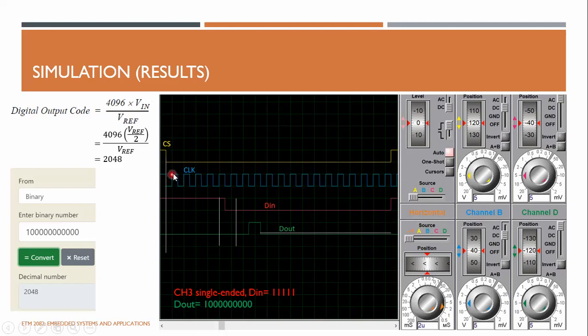Using delays and the right frequency, you can set the other clock pin low and high likewise. During this period, the DIN could be set to high or low depending upon the input channel and whether it is differential or single ended. So you can write a code using while and for loops, and then the device will output the digital value.